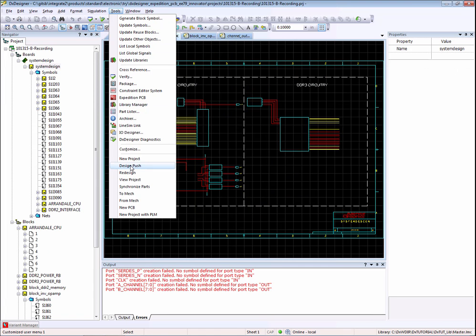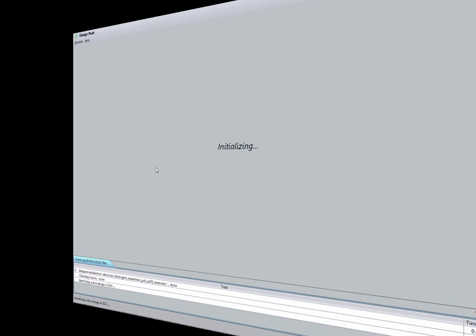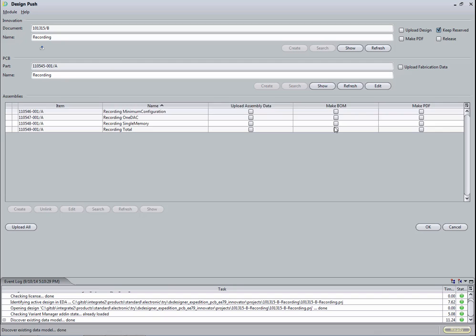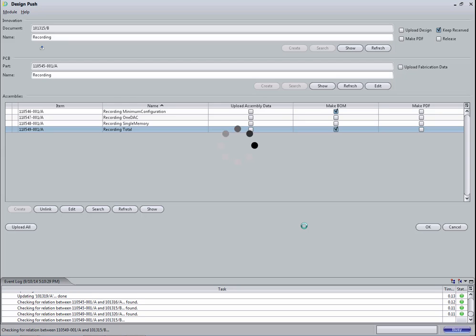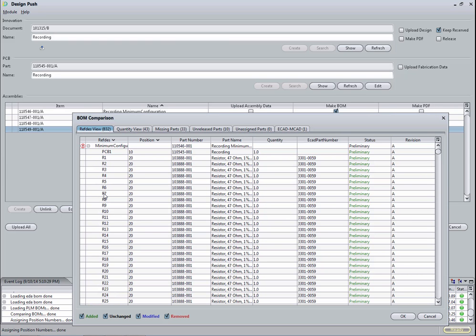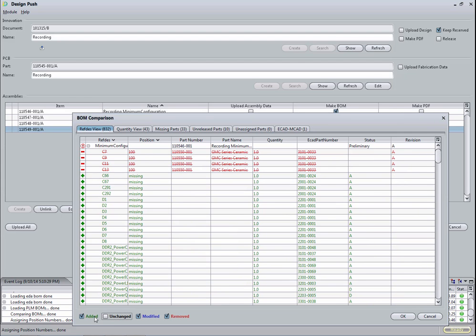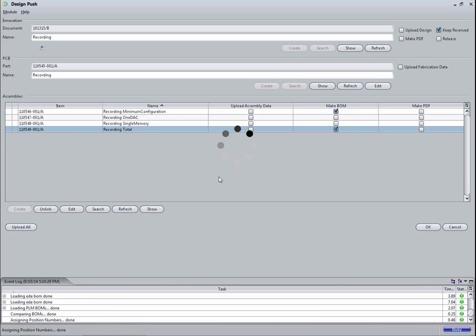After that, we start the module Save once again. In our case, the changes in the bill of materials are now the main point of interest. Therefore, we just select the bill of materials for the relevant 2 variants. Again, we see a BOM comparison dialog, where we can now see the difference to our last version. Our missing parts are of course still existing, because nobody has defined them meanwhile in the PLM system. In our case, the warning message can still be ignored.